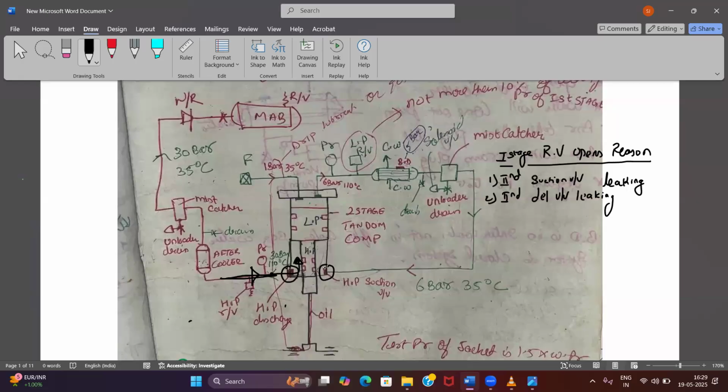No, sir, because the pressure will always be higher. It will not allow the suction valve to open on its own. If the suction valve is not opening, but the first stage is continuously delivering air, it is a positive displacement piston pump, so the pressure is going to rise and the relief valve can lift up. Do you understand? Yes, sir. Now everyone understood this much?